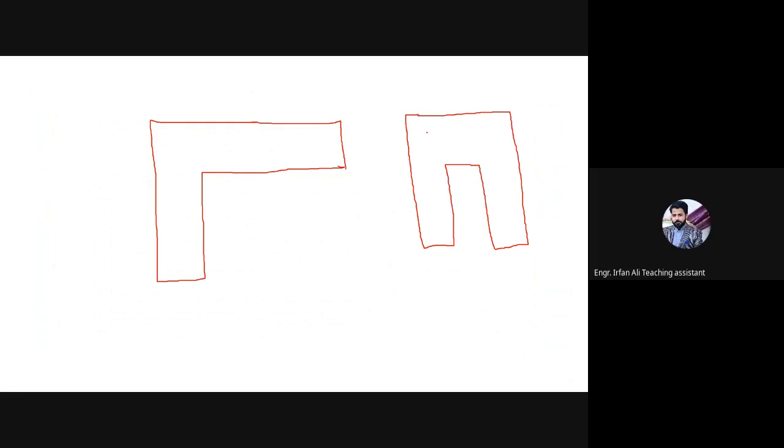So I have explained earlier, if this dimension is greater than 200 feet, this is the general thumb rule, and there is some requirement of the code. There is an ACI special code for this. You can search on Google. So you have to give an expansion joint.